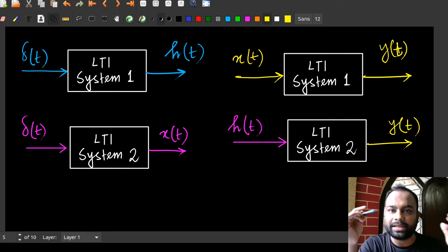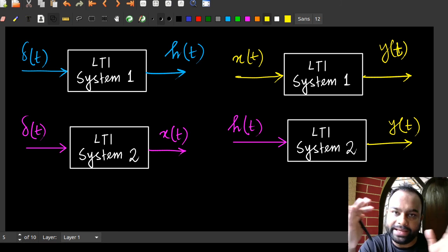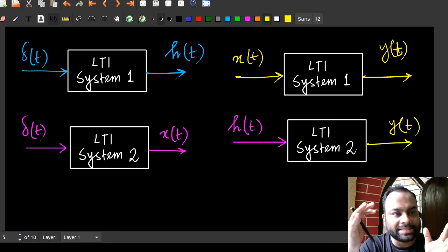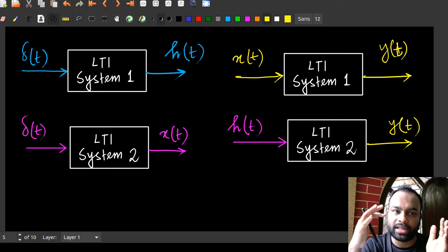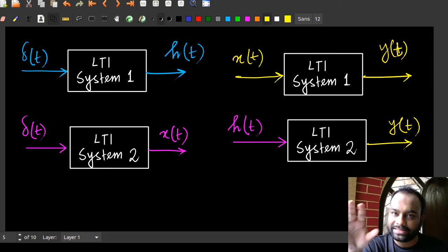So in this understanding, we can very easily say that LTI systems and their responses are interchangeable in nature, and we actually established that idea with that example. I could have an empty hallway and play my music there to hear how it sounds in an empty hallway. Or we could have the impulse response of the system, because it is entirely representative of the system.